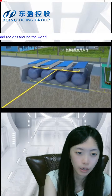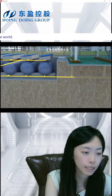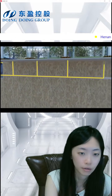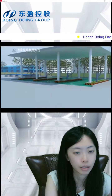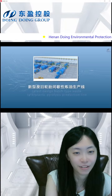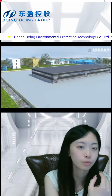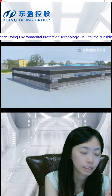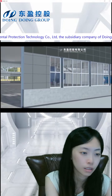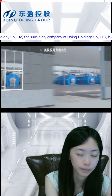And if your raw material is a hazardous waste, then the heating temperature is higher than the conventional raw materials. It is much more than 400 degrees. So that's why we use stainless steel. It's not only because the hazardous waste contains corrosive substances, but also because it has a very high temperature.